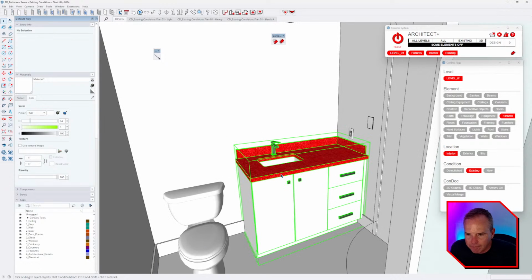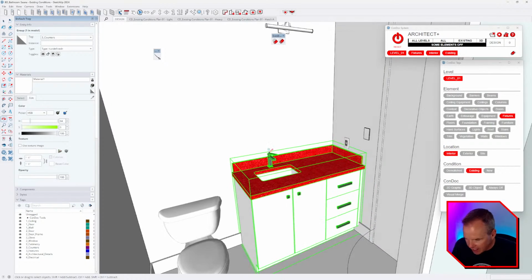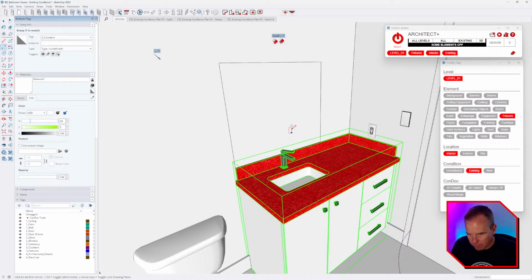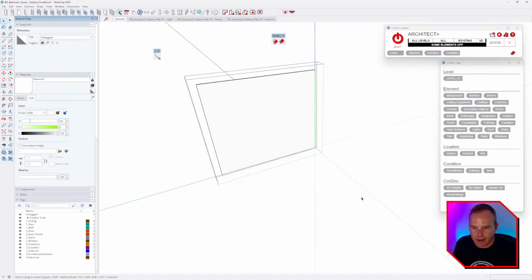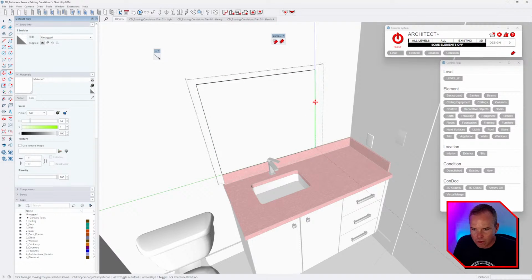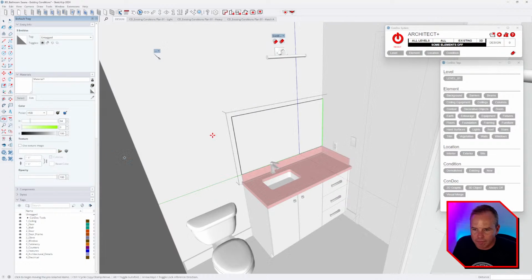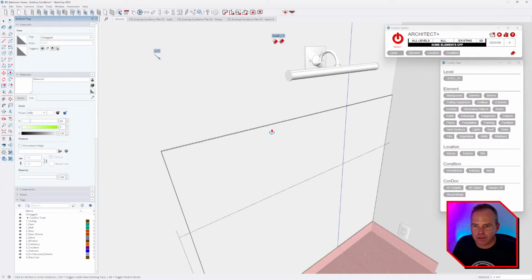So, you know, again, part of the vanity, this is level 1, fixtures, interior existing. We're good. I'll just throw a mirror on here, like this, and then I'll pull it out by, say, 1/4 of an inch, and then I'll triple click, make it a group, and then scoot this over like that. And then I'm going to push pull it up like this.